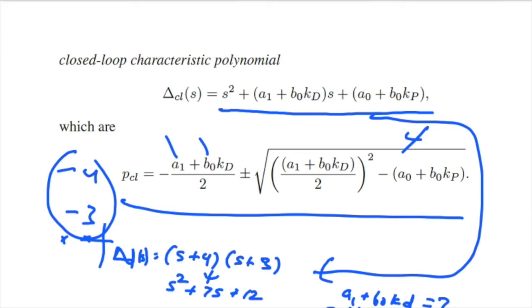So I said I want to place my poles at -4 and -3. These are the desired locations. So the characteristic equation then is (s plus 4)(s plus 3). Those are the locations where you want to place the poles of the closed loop transfer function. We'll see how important that becomes, because sometimes your open loop can have poles at +4 and +3, and then you can drag them and make it a stable system. So an unstable system can be made stable by applying a controller.